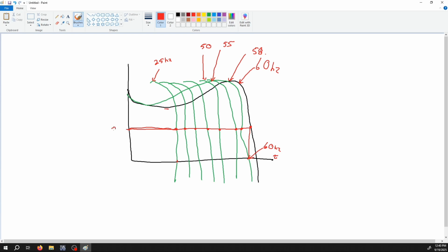So with a VFD, you get the rated torque all the way through the speed range. And it's because we are changing that frequency. Now, the torque value does not directly equal our power.